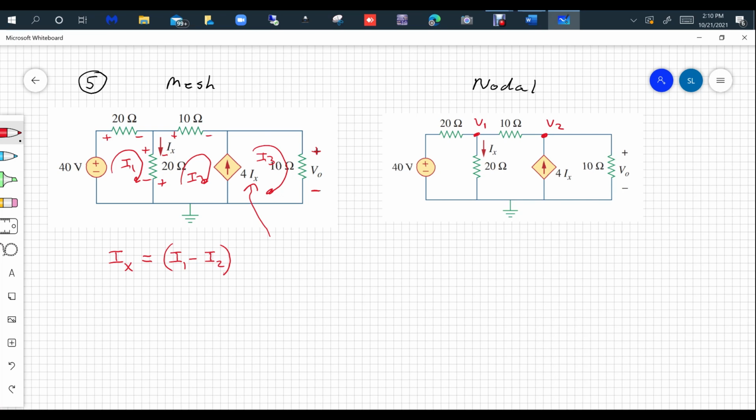Why come up with a voltage of V2 when you know that voltage out there is V out? They give it to you here. And this is all the same point here. So don't put in what I call dummy variables. It just adds extra equations. So that's clearly V out or V naught.